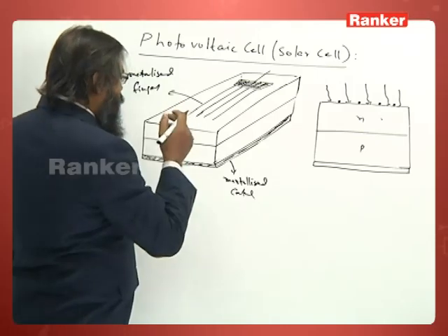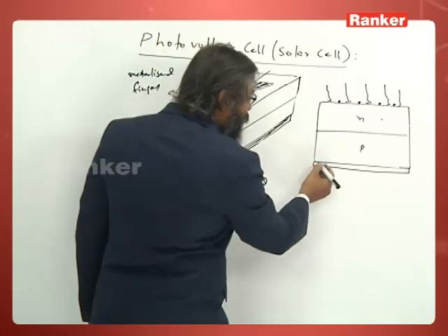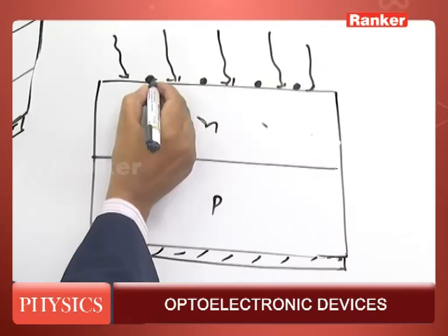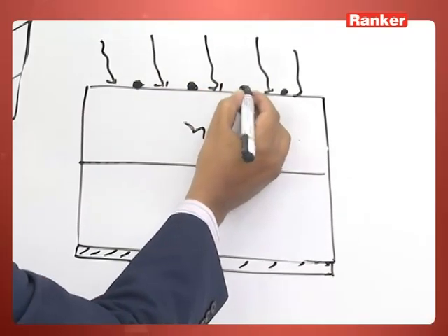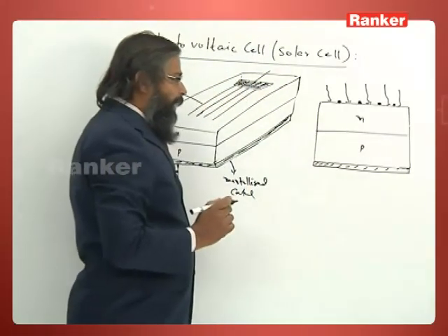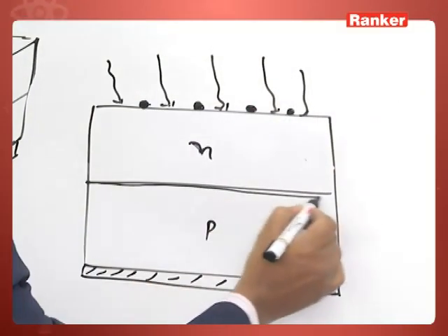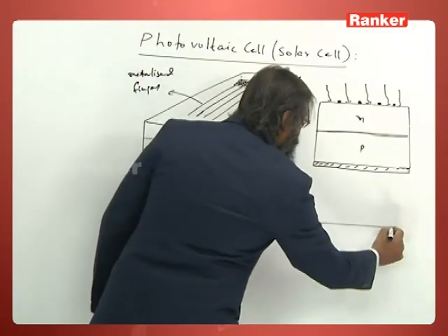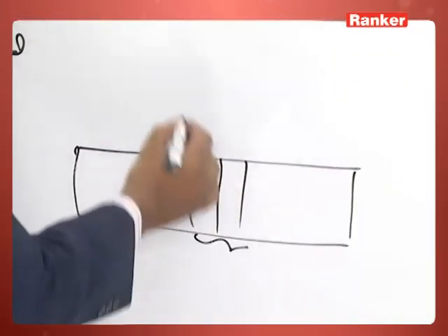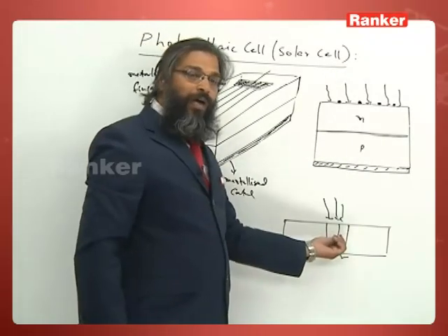You see, and this is its cross sectional view. This is the metallic contact with the P side, and these are the fingers I have shown, and this is N type. Now, light has to fall on the junction. When I represent this by a block diagram, I represent that this is the junction and light falls. Actually, light can't fall like this. This thickness is very small.